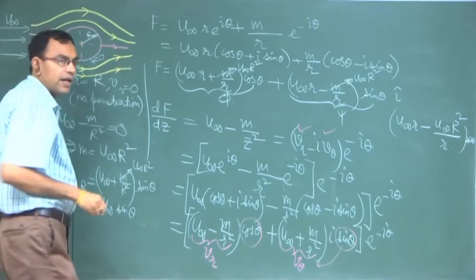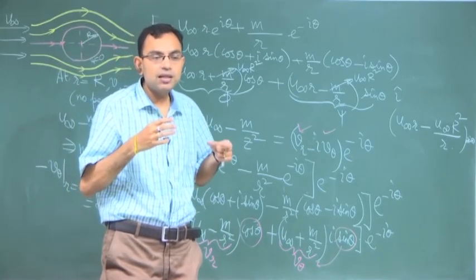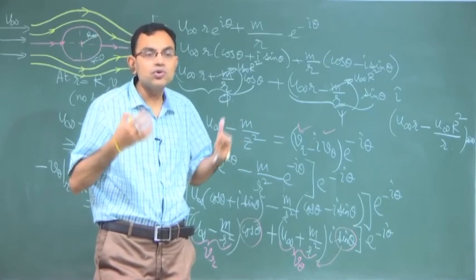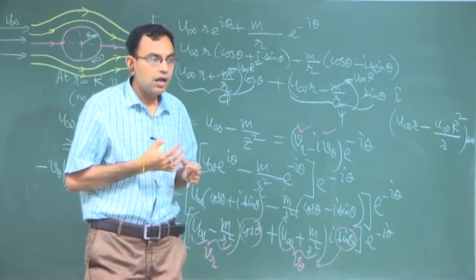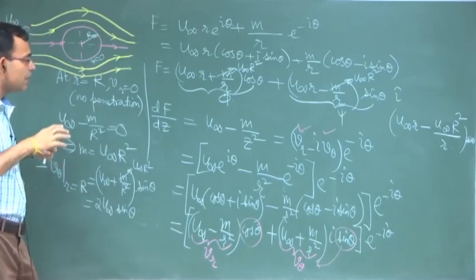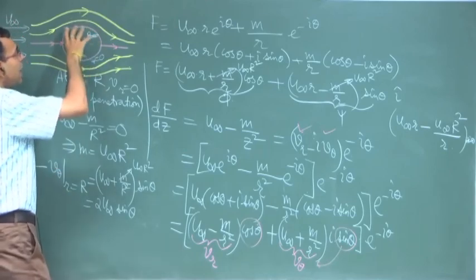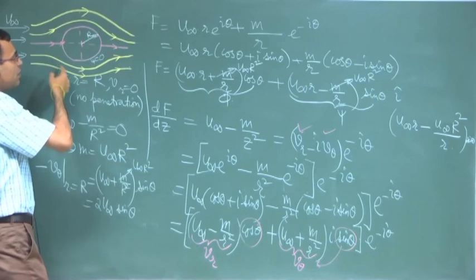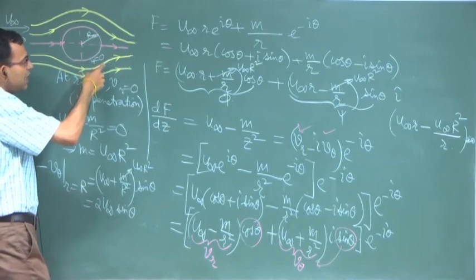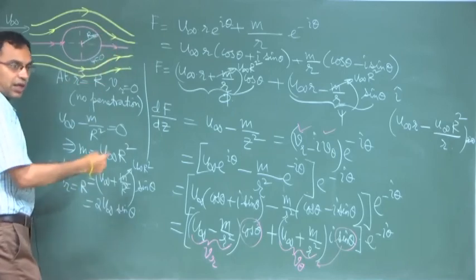This symmetry can be broken if viscous effects are brought in, and this symmetry breaking due to viscous effects can give rise to a drag force on the cylinder. However, without considering the viscous effect, we can get significant insights on the pressure distribution on the cylinder, at least up to the region over which this kind of streamline pattern is maintained. If there is viscous effect, then there can be a phenomenon called flow separation at the back face of the cylinder, also called wake.